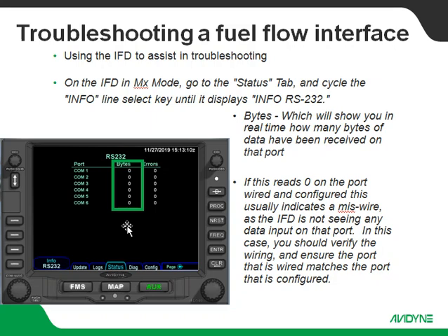If that reads as 0, that means the IFD is not seeing any data on that port. Now, something to keep in mind is if you've just configured the port in maintenance mode on the config tab, going over here to the status page may not necessarily come to life immediately. Usually whenever we've made a configuration change in maintenance mode on the config page, we always recommend doing a hard power cycle on the IFD for that config change to take.